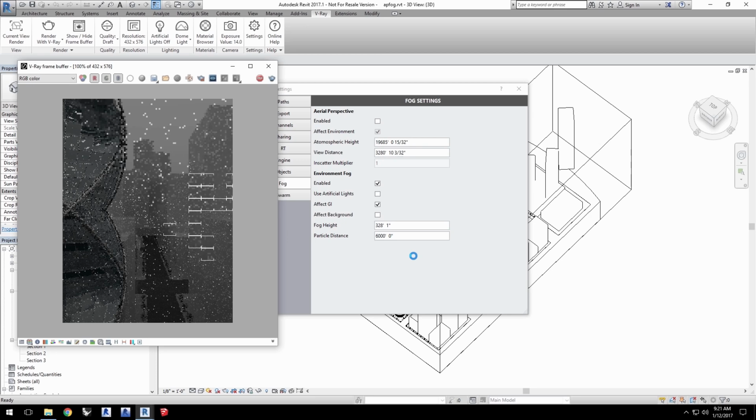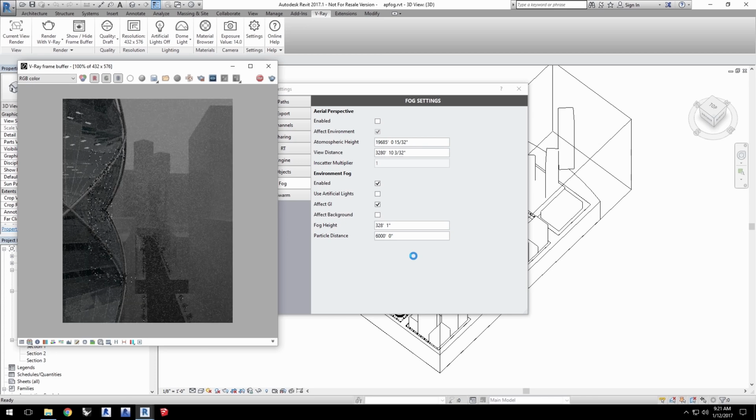Render the project now with the white solid color dome light and the less dense fog, and you'll see a dark result. Now, since we're using a fog like this, we're muting the amount of light that is in the scene, so we should be adjusting the camera's exposure to compensate. However, you can also enable post-processing effects in the VFB to make color adjustments to the image directly.